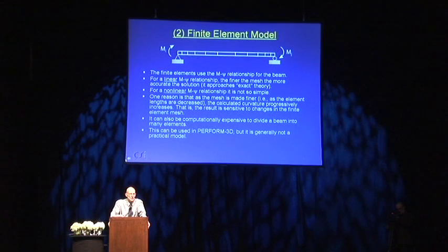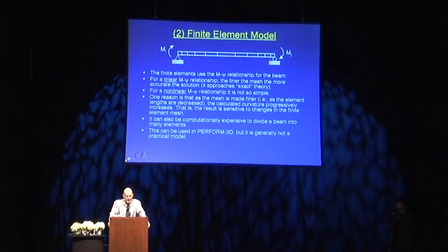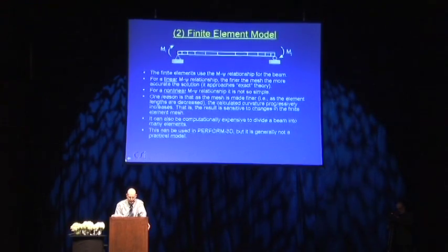If you really want to be exact for nonlinear, you have to use a lot of really complicated fracture mechanics theory. It's not simple nonlinear behavior anymore. It's much more complex, way beyond anything which is practical. So a finite element model may be good for linear, not so good for nonlinear. I'll say more about this later when we talk about walls, because a similar issue comes up.